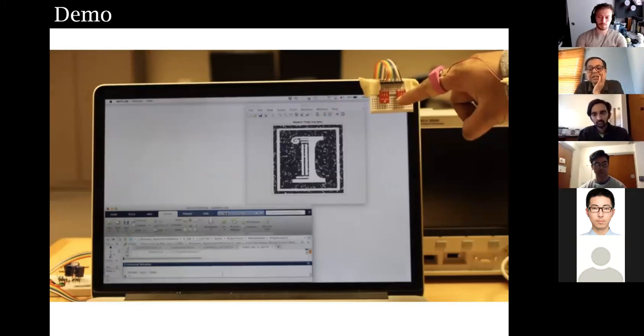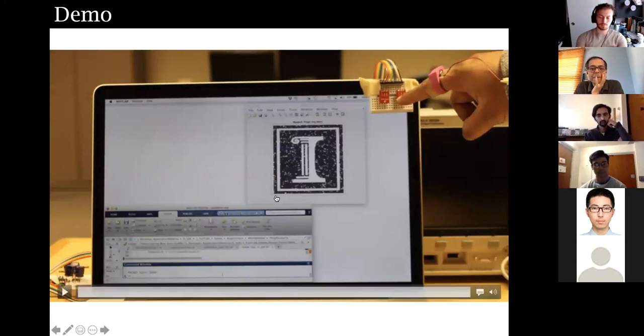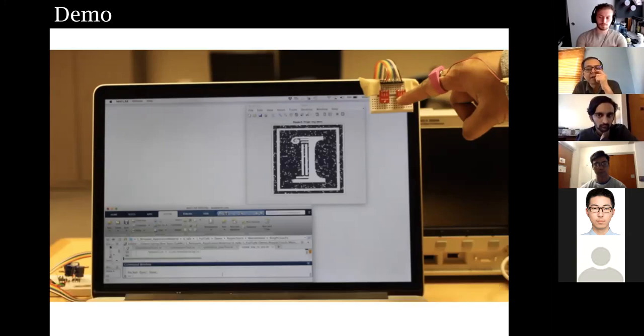It's around 6 to 8 kbps, but there are a bunch of errors. Look at many of these blue points becoming white, and there are some white dots in the blue parts as well. In communication systems like Wi-Fi, the receiver gives feedback to the transmitter saying this bit was an error, can you retransmit the packet?